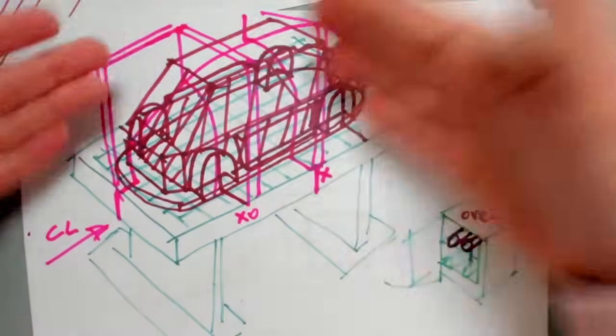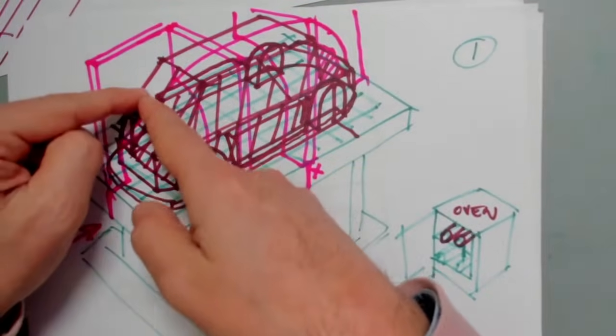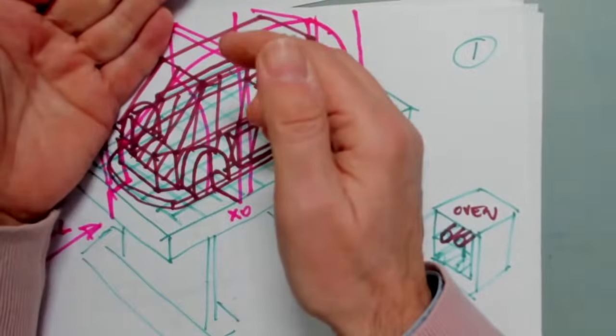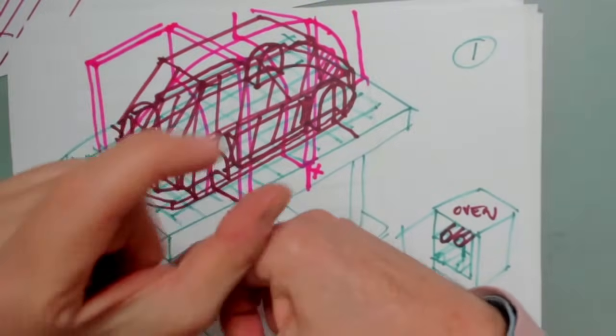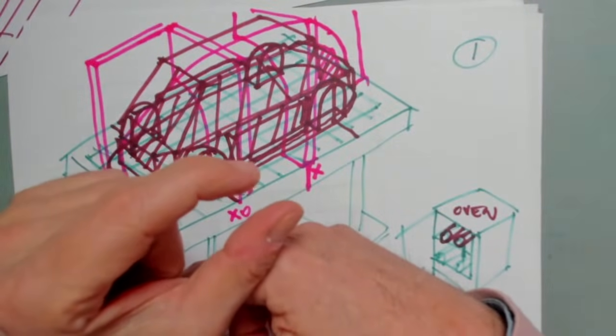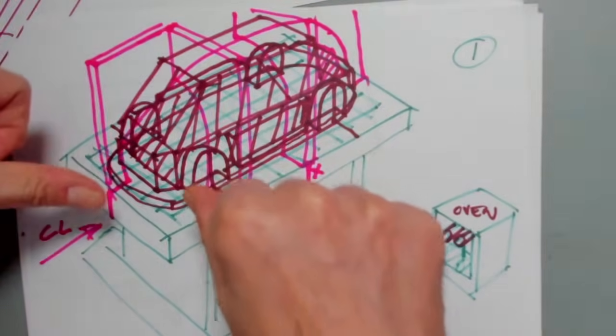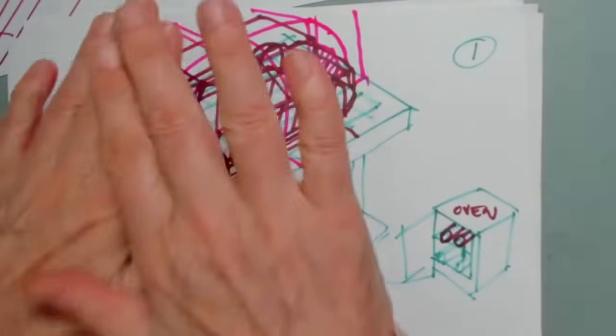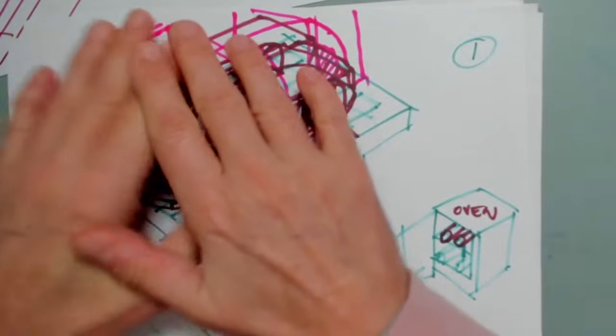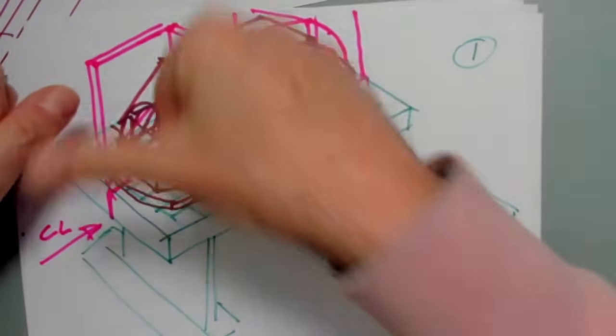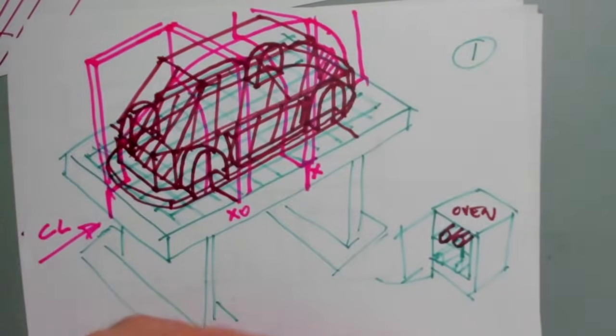When you have the sections, you will see the gap between the structure and the section. If it's more than 1 centimeter, it's too much. Therefore, you can put some extra soft foam glued inside. If it's not, then you can just go straight with clay.